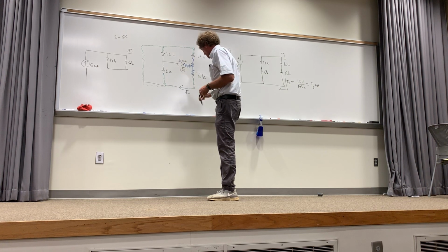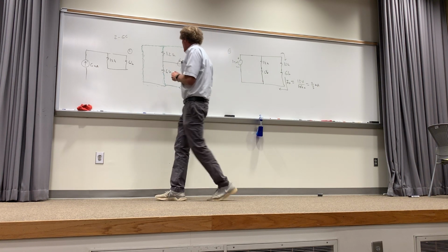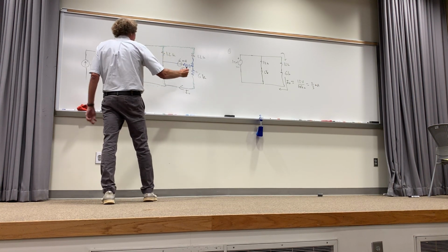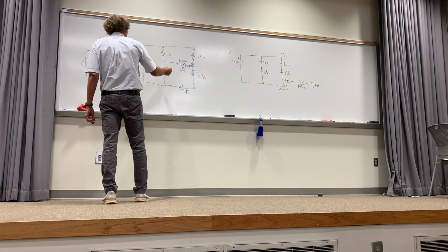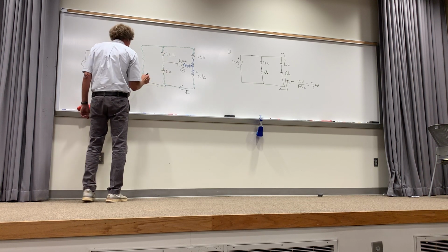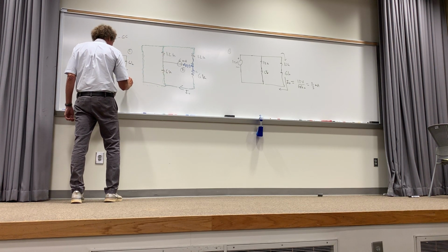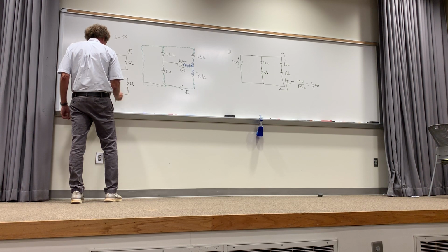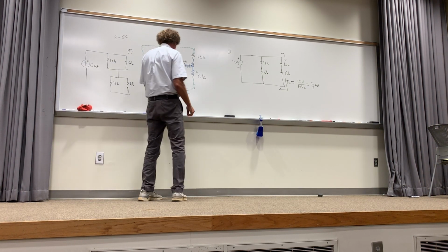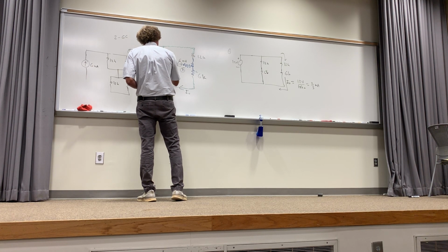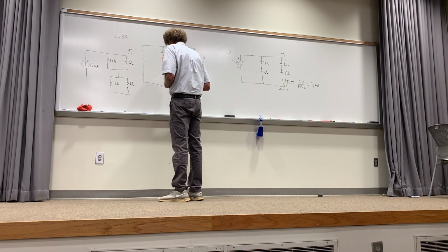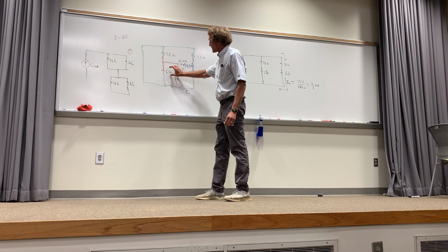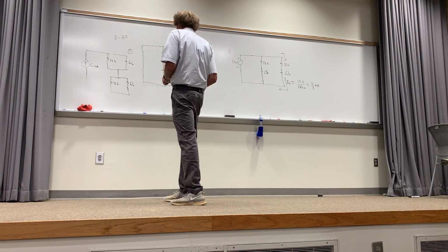Because I've got this part too. So now I need another color marker, and I'll go on the other side of this 12. When I come through there into the green, I have two resistors that I hit: the 6K and the 12K over here. Now I take another colored marker, go to the other side of the 12, and I'm back to the actual start. Anything between the red and the green is in parallel too. So if I look there, I have the 6 and the 12 in parallel.